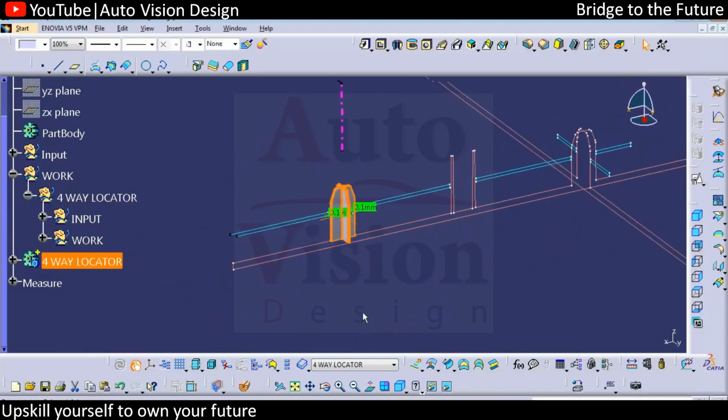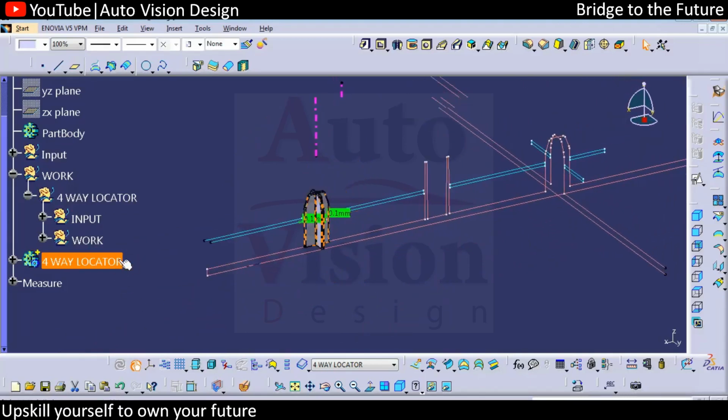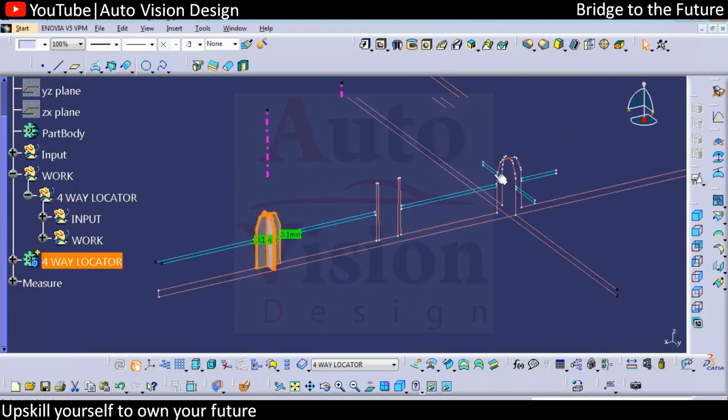Whenever we need to create this from one side to the other side, we have already created the four-way locator, and we need to create the two-way locator over here. So how can we create that? Simply we're going to use the power copy. So what is a power copy? Power copy is used to have multiple instances.